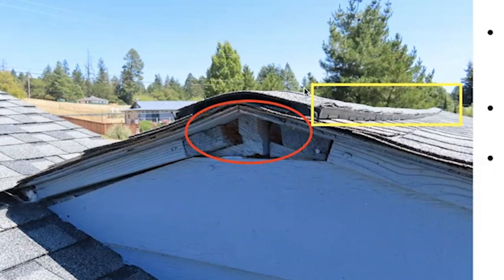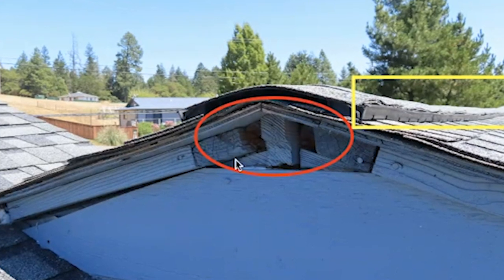The other thing is this in the red circle. This is an opening right at the ridge of the roof that is not screened. So it's a wide open area for embers to enter. And before that, you could have had debris entering. You could have had rodents entering or birds entering, building nests in there. So there could be a lot of fine fuels just inside this open area. You really need to screen this area or block it more. It's easy enough to block this with a metal product, actually, to enclose it so embers and rodents can't get in here.